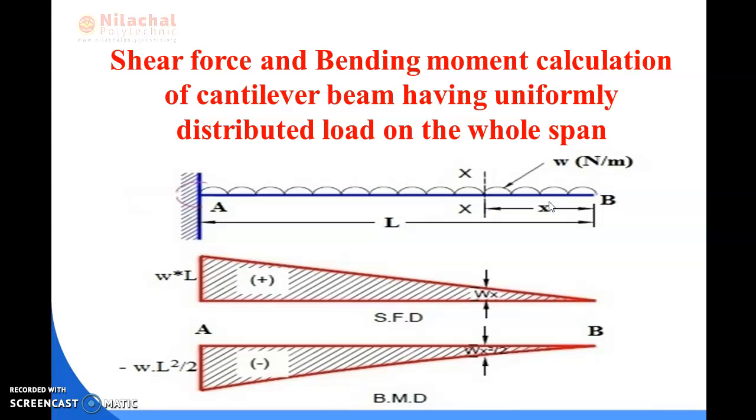In that way we take load, that is W, into distance, that is X, multiplied by the perpendicular distance, that is X by 2. So as a total your value should be W into X by 2. Because the loading system is at the right side of the section, it will give this kind of moment in this direction, which is a hogging moment towards the cut section.